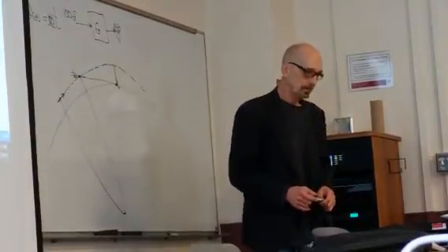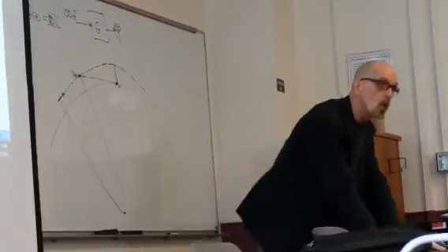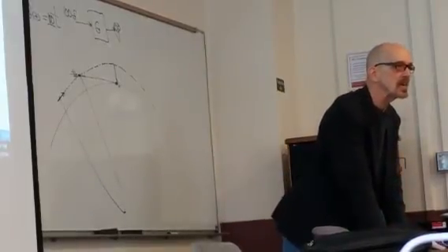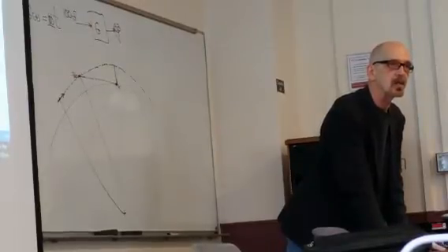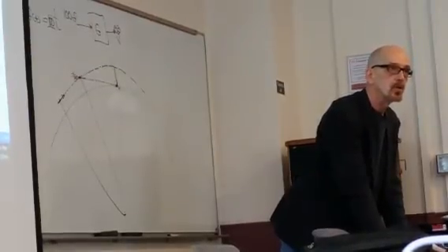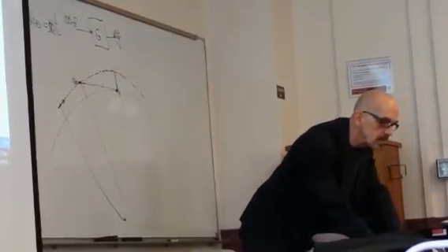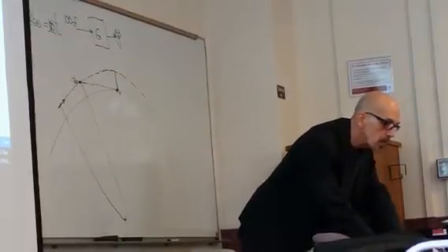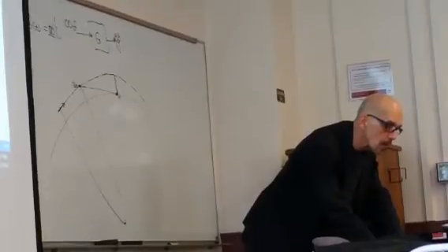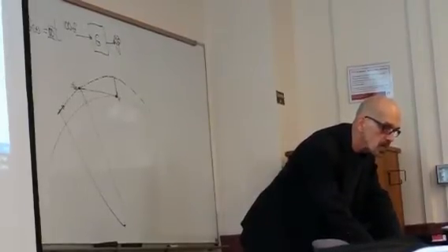When you say steady state, it doesn't mean everything is static. All it means is the transient dynamics are gone. So you're tracking something without those additional transients. Consequently, it'll track a ramp with a slope, say, gamma with steady state error.